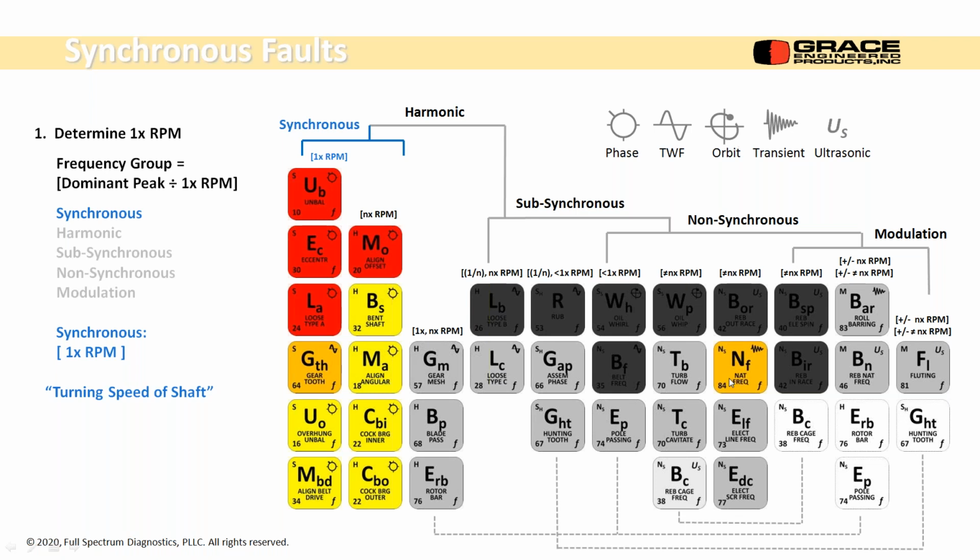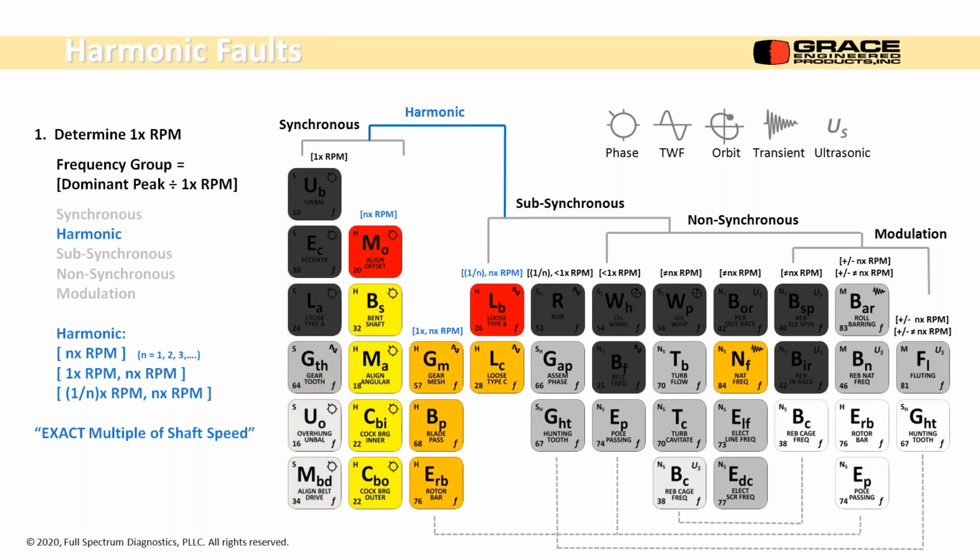The natural frequency is a frequency based on mass and stiffness. It's not based on blades or gears or anything like that. It is all mass and stiffness. We have to disprove that it can occur anywhere. It's non-synchronous, but it can be close to running speed and still amplify. So we have to prove down the road if this is a problem or a phase problem in the third part of the analysis. So the first 2 columns are synchronous, the turning speed of the shaft.